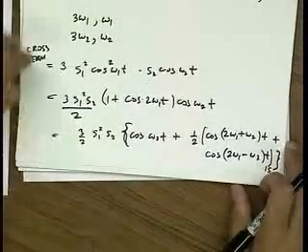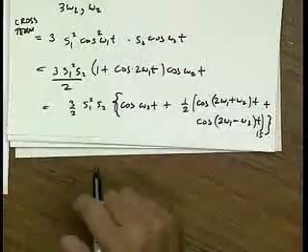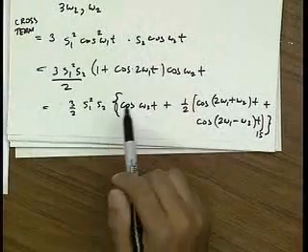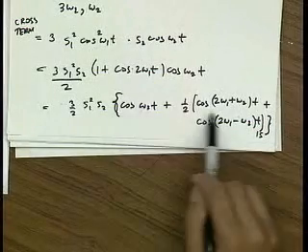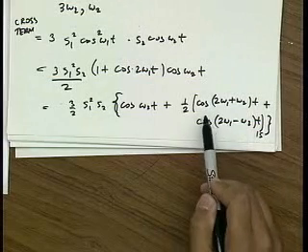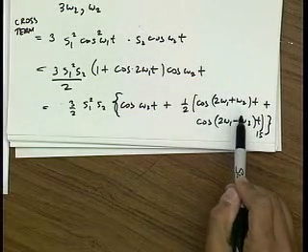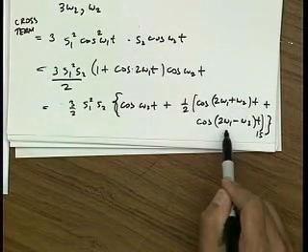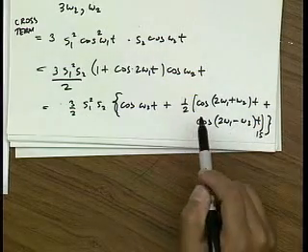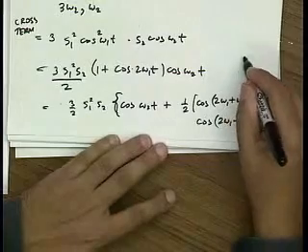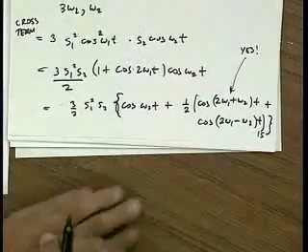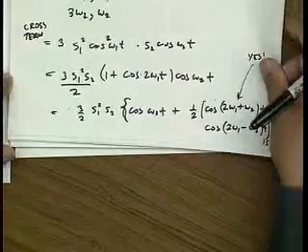Okay? Now this is again something we've seen before. This is just more generation of second harmonic. These two terms are the intermodulation terms that we're looking for. We can see that we generate a tone that's 2 omega 1 plus omega 2, it's a new frequency, and 2 omega 1 minus omega 2. So these are the very important intermodulation terms. Just say, yes, that's what we're looking for.